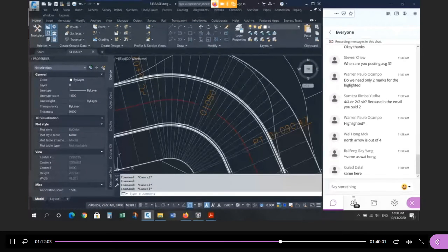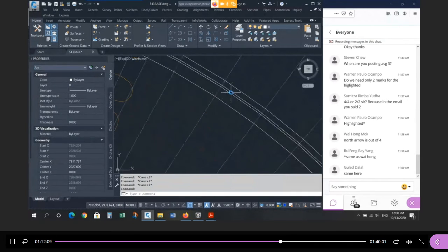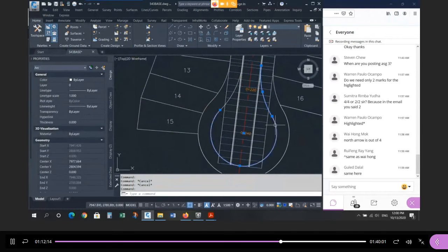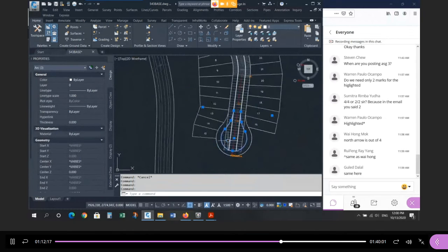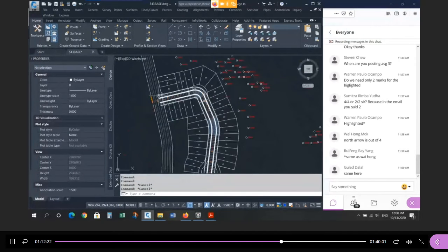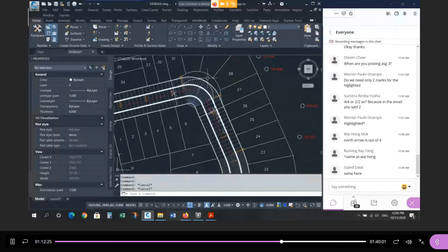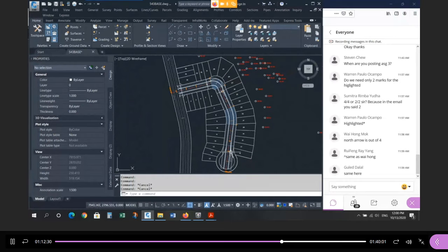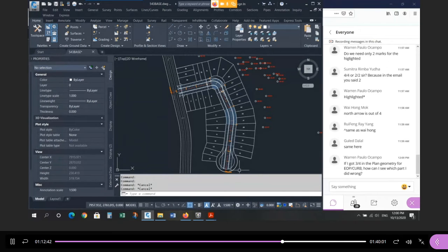And again, see how the edge of asphalt on the inside is in the right spot, but on the outside, the edge of the gutter line should be here. Right now it's drawn over here. Same thing with the cul-de-sac. It looks like it wants to go straight through. It needs to widen and go all the way around and back again. So that's incorrect. This does not represent, and this does not represent, and neither does the intersection. Tomorrow I'll show you how to widen the corridor, the elbow, and the cul-de-sac. But if you can get this much done for homework, it doesn't take long, then you've got the basic model. Then we just have to tweak it a little bit to get the true representation around the widened spots.